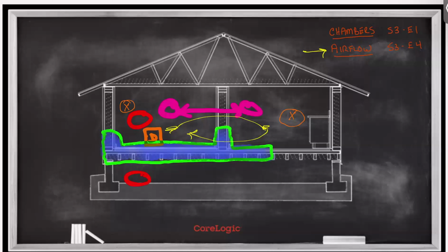But here's where we commonly overlook our chamber setup in humidity control. What I've just drawn out for you addresses well the visible, accessible surfaces within this environment. What it does not address very well are the surfaces inside of this interstitial cavity, or the surfaces inside of this interstitial cavity, or if this is a hardwood floor, the surfaces beneath this hardwood floor. So as we establish this chamber and this airflow so that we can control humidity, you have to control humidity not just in the open visible space. You have to control humidity in each space where water is evaporating.